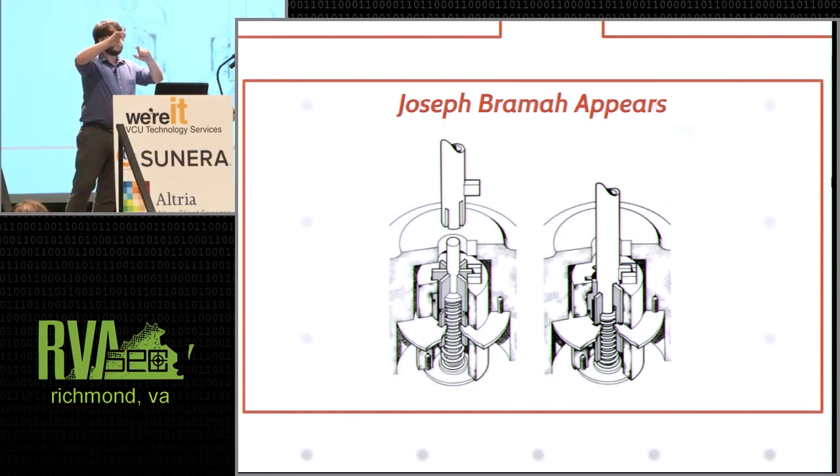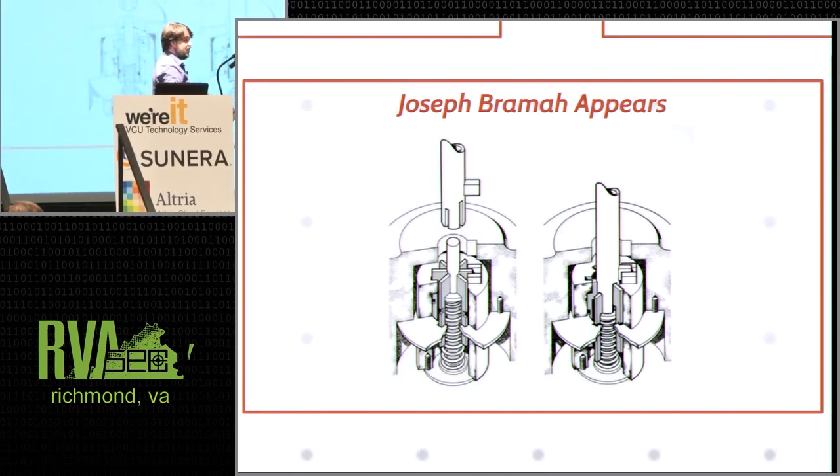The length of the slot corresponds directly to the length of the sliders, which you see at all even depths on the left, and then with the key inserted, all of the sliders will be depressed different amounts by the key. There's a gate in the sliders that correspond to the depth that the key is going to push them to, and then that metal ring in the middle, it allows them all to spin through.